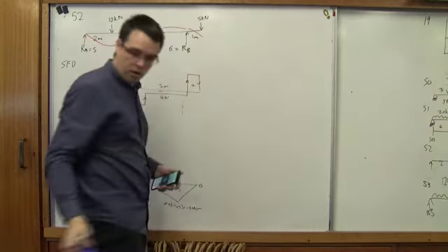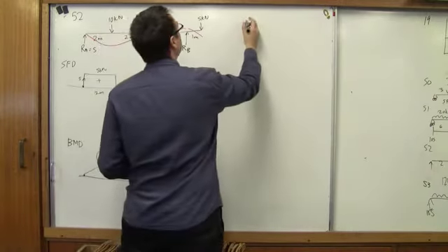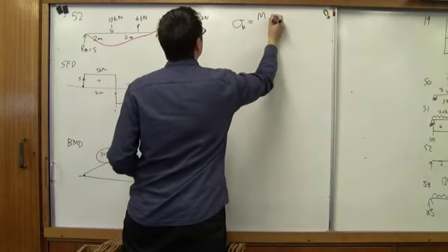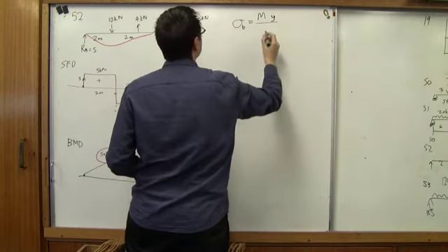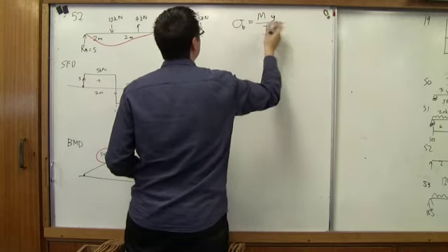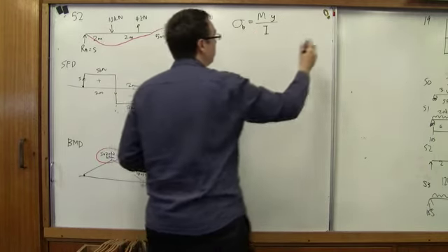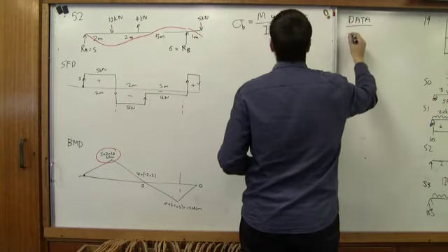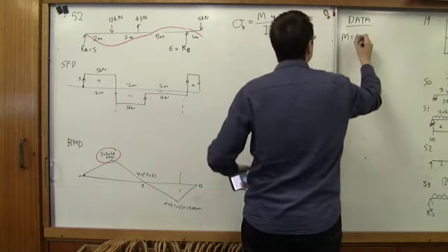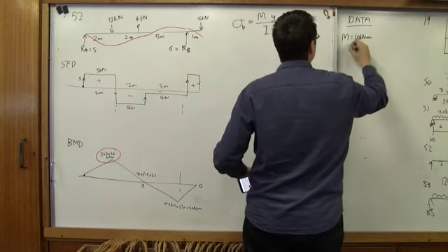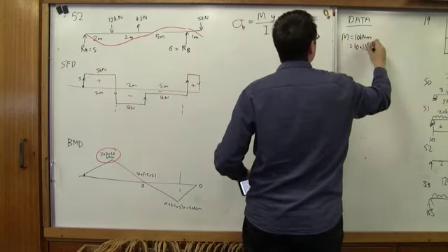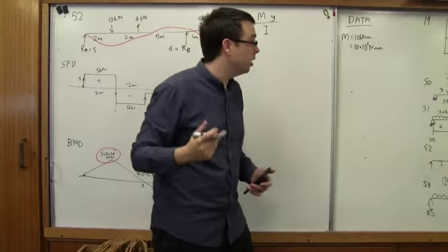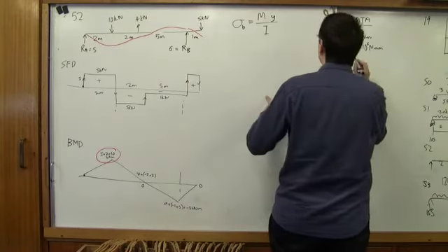So our formula for bending stress is sigma b equals M, the maximum bending moment, times y, which is the distance from the neutral axis to the extreme fibre, divided by I. So let's have a look at our values here. I'm going to write data over here. We're saying that M is equal to 10 kilonewton meters, which is equal to 10 times 10 to the 6 Newton millimeters, because we'd rather use Newton millimeters. We go together like megapascals and millimeters squared.